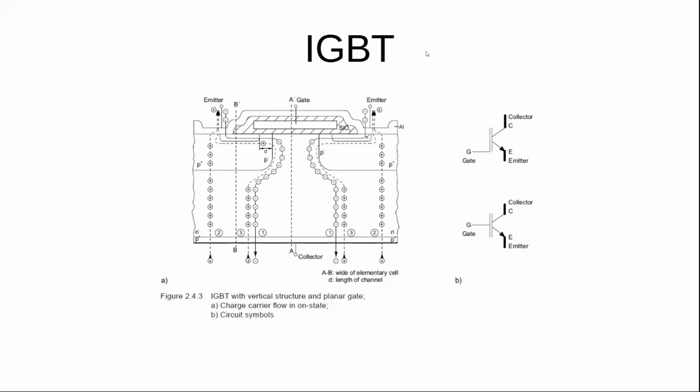Okay. And this is a benefit. Doing voltage control is a real benefit. If I was comparing a MOSFET to a BJT, the drive system would be easier because I'm doing voltage control. I'm switching it on and off using a voltage.